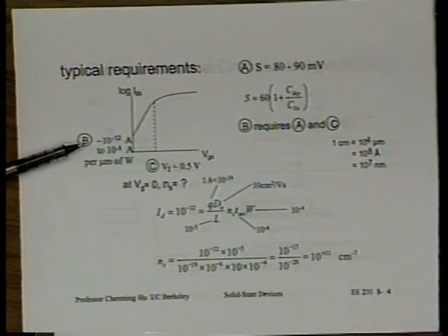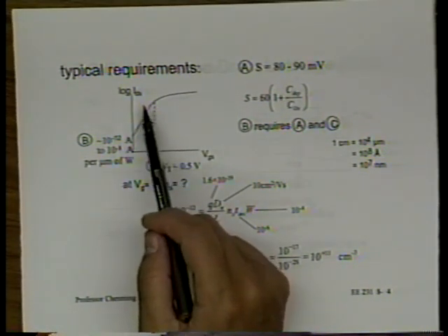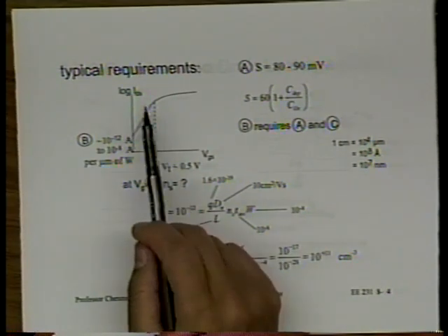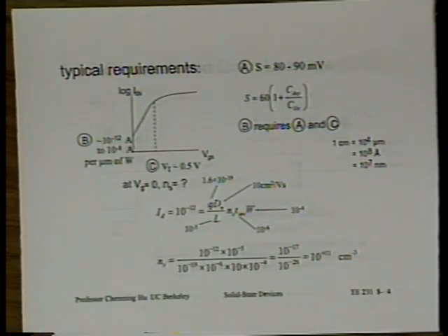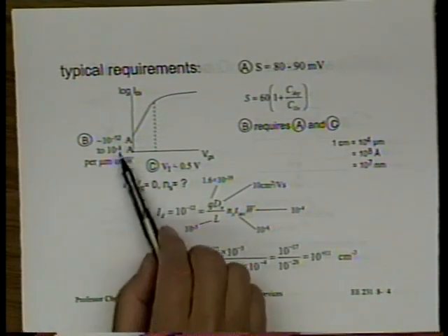For handheld low power applications, we want to hold them to very low power, low leakage. On the other hand, for high-speed applications where we really want to design a transistor with as small VT as possible so that we can get high speed, we're willing to tolerate more leakage.